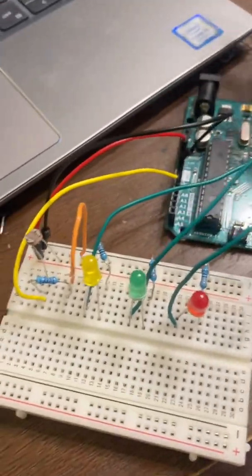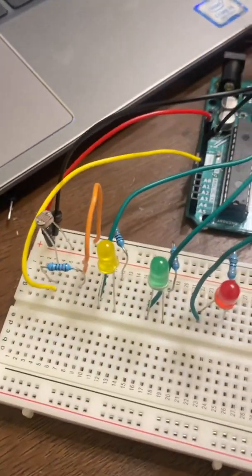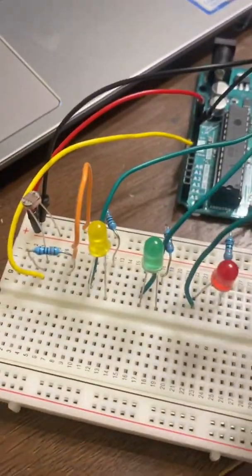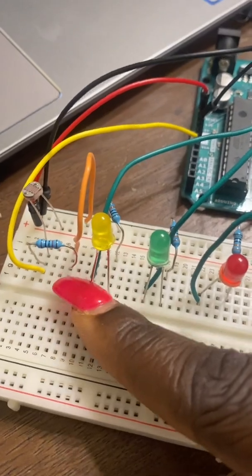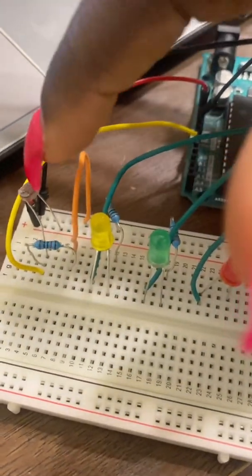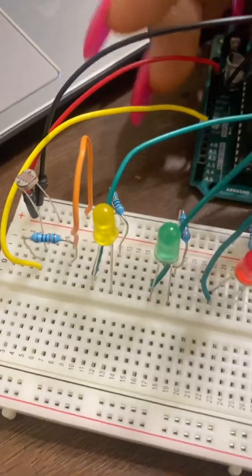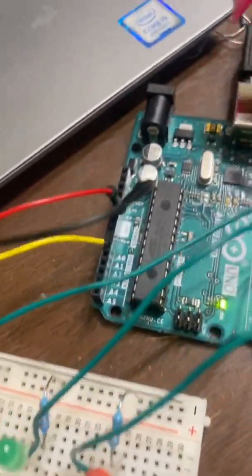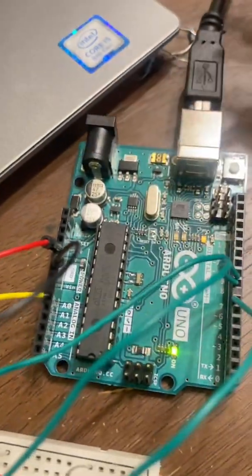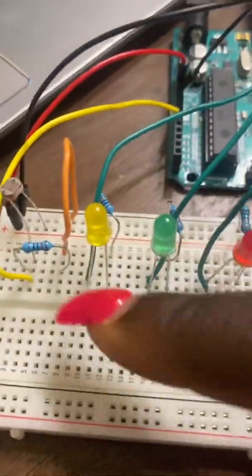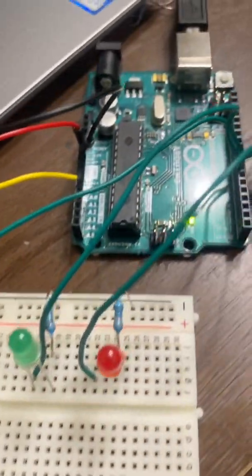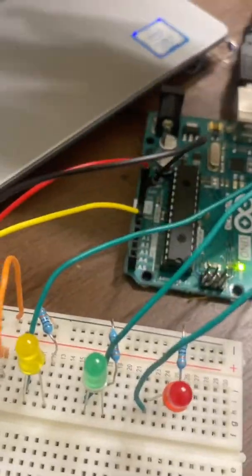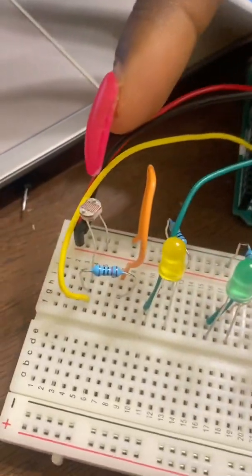In this case, we have the LDR connection to the Arduino. Here we have the light dependent resistor connected to the pull down resistor connected to the ground, and the LDR connected to the positive side of the breadboard, which is in turn connected to the positive side of the Arduino. In turn, we have all of these LEDs connected to the pins and to the current limiting resistors for each one of them. We just want to see how this LDR works.